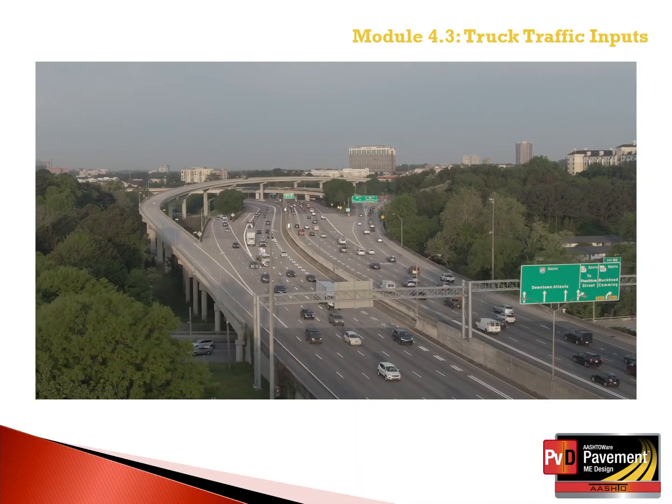Truck traffic volume and weights impact the minimum requirements to ensure acceptable performance of a pavement section. The Pavement ME Design software combines the number of trucks and the weight of the trucks with the climate data just delivered under Module 4.3 and the layer properties to predict pavement damage and distress throughout the design period itself.